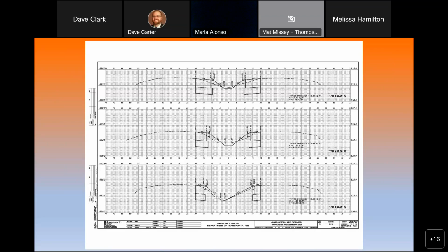You've got your elevations that run up and down the sides. Down below has your distance out from the center line. Your elevations here give your station that this particular cross section is at. It gives you an idea of what they're putting in: their aggregate base, sub base there. They're doing their paving. They've got their shoulder. They've got some dirt work and so forth here.